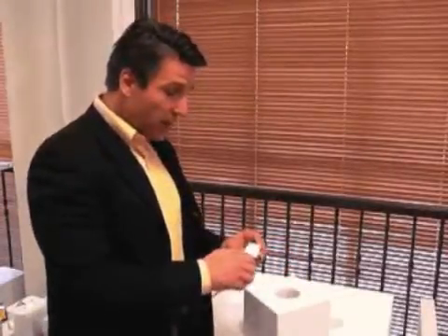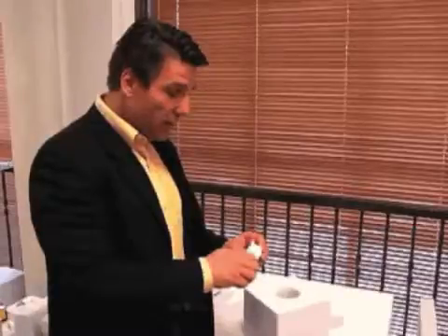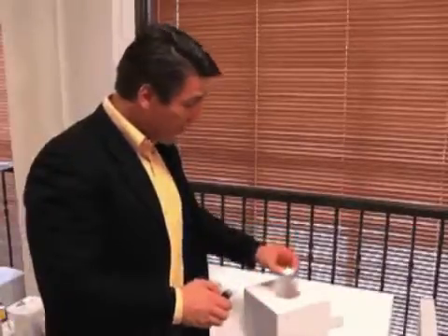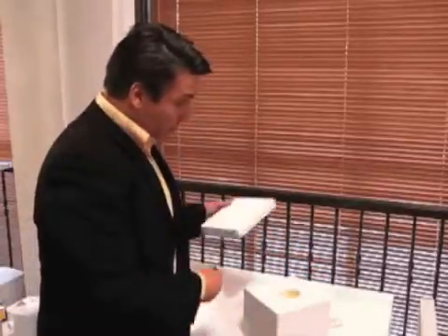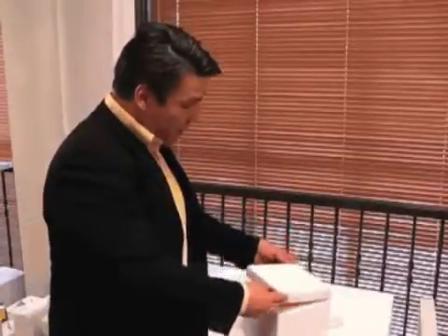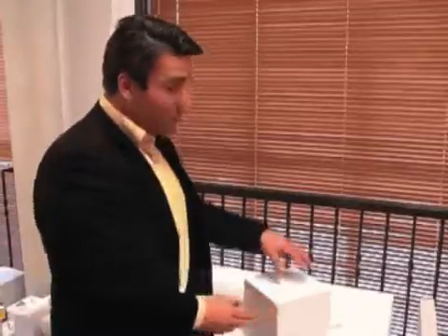I will light a candle. I will put the candle into the 2.5 inch hole and add a lid on top. So after approximately 14 seconds, the candle will extinguish, which shows you basically if you have a building where it starts burning inside, and you have AAC walls, floor and ceiling, the air will not come into the building in order to keep the fire burning.